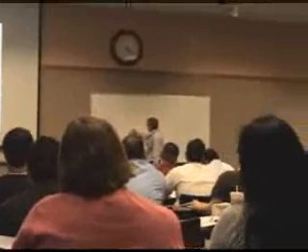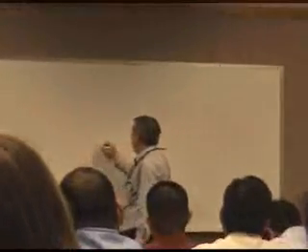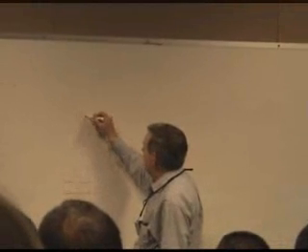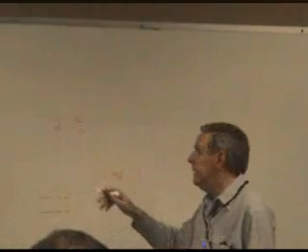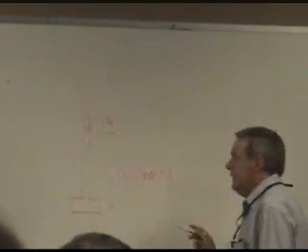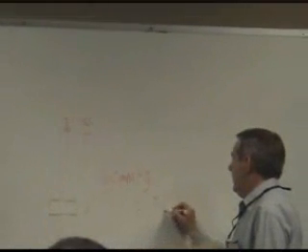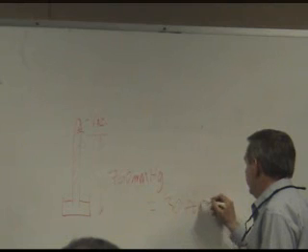If you fill this thing with mercury, then you end up with your 760 millimeters of mercury for atmospheric pressure. But up here, you basically have a vacuum, or basically the vapor pressure of mercury. So 760 millimeters of mercury, if you translate it to water, it's roughly 30 feet or so of water.